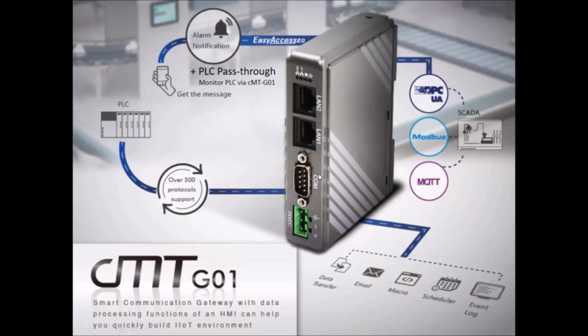And also, it does more than this. So it supports data transfer, which will help you to transfer from one of your devices from the Ethernet to a serial device, or from a Siemens to a Mitsubishi PLC. And we support email and macros for you to do some calculation and to automate your conversion, or maybe some alarms if you want, and a scheduler and event logs.